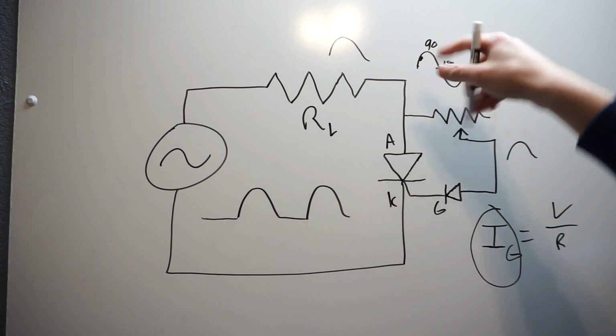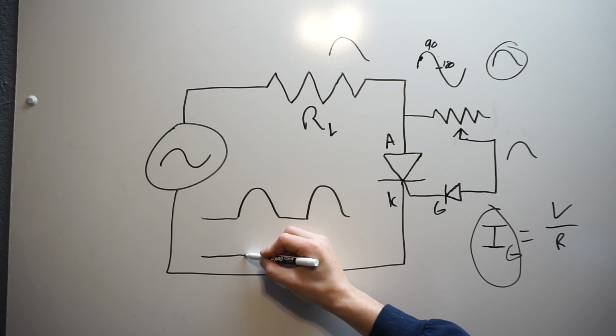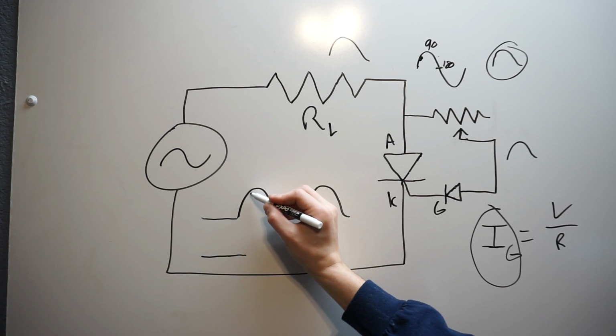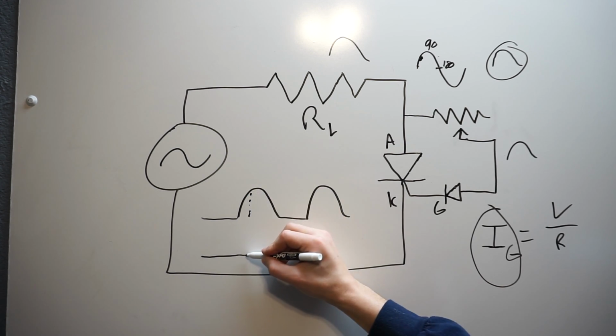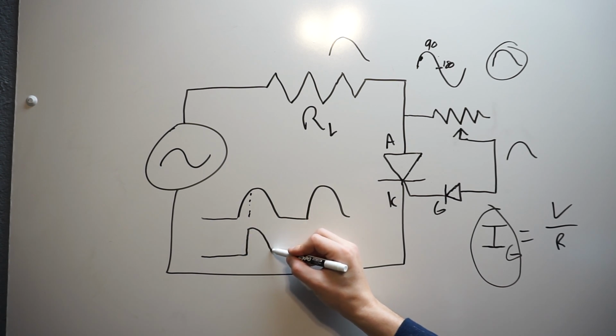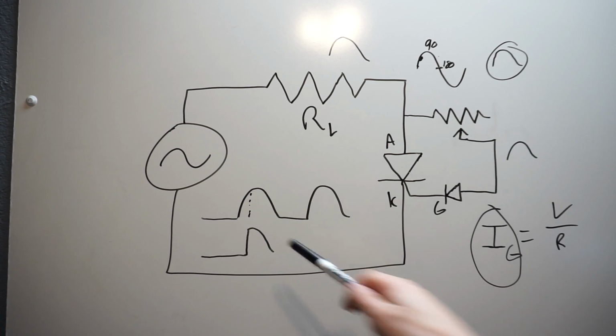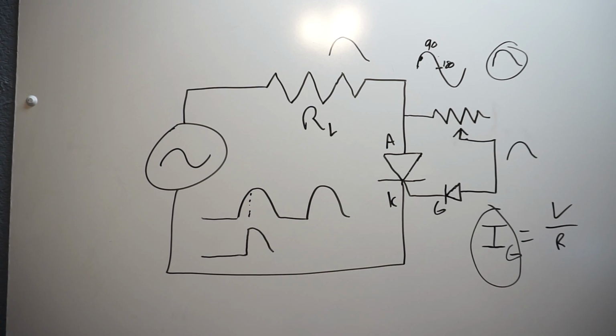Well, with this idea up here, we can choose what part of the actual phase to start at, and let's say we wanted to start it right here, we can cut off the rest of that phase, and it'll just jump up right there, and you'll only do half or whatever portion of the actual cycle you want. And this can get into what we call phase control. This is how light dimmers work. This is how large motor controllers work for AC motors.